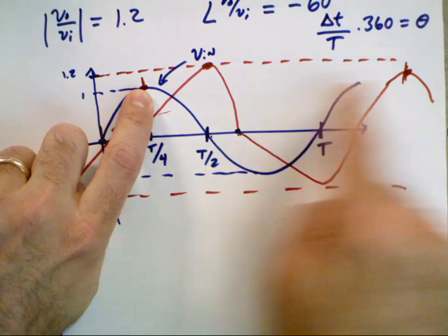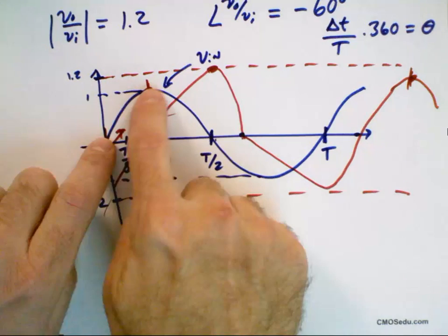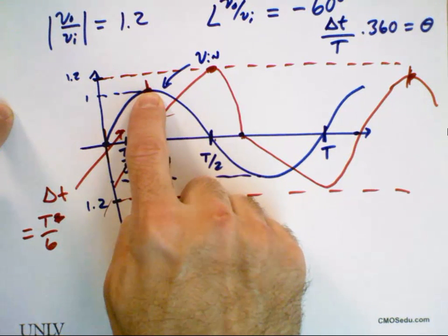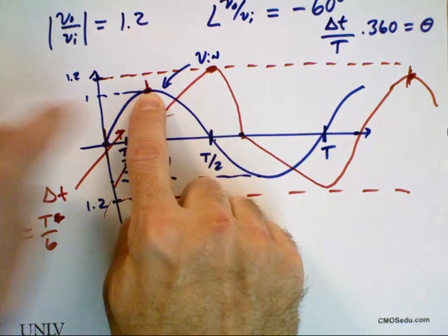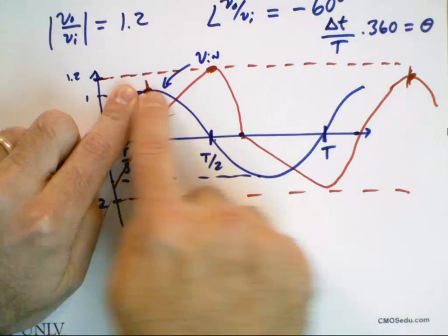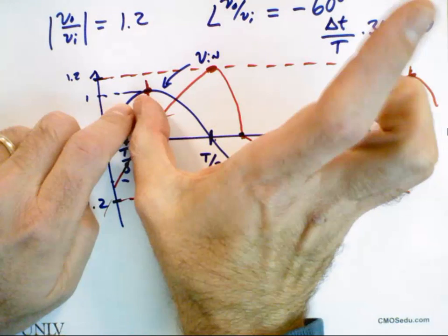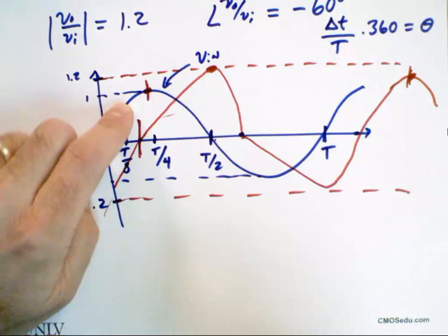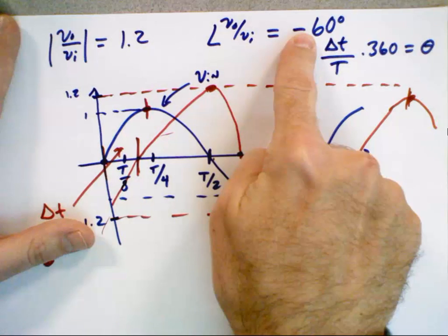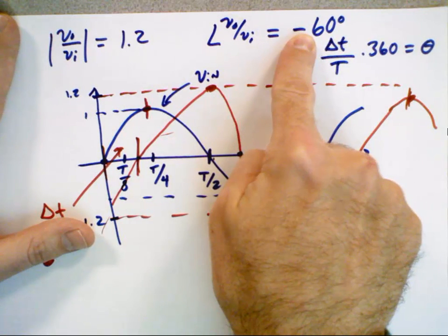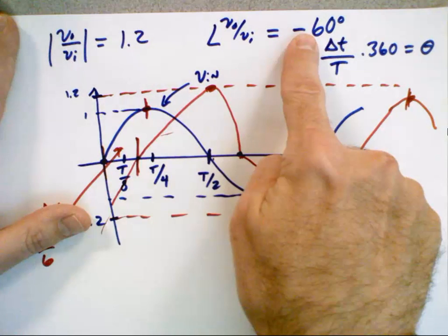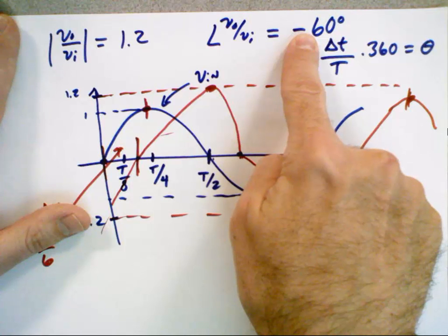Okay? What if I compare this point with one of the outputs over here? Positive. But what would also happen if I did this? The phase shift would be over 360 because the time delay is over T. So the key points, if you take away anything here: negative means output occurs after input. Positive means output occurs before input. You can throw the leading and lagging in there. Negative means output lags input. Negative means input leads output.